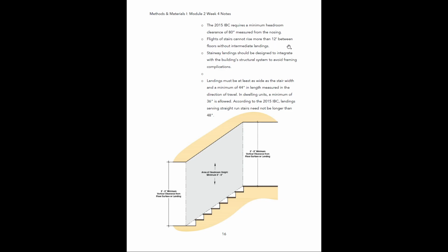So if you are going up more than 12 feet, you have to have a landing somewhere in that stair. Right? So let's say you have 13 feet. You're probably going to have to put a landing in the middle of those steps, just because of codes.